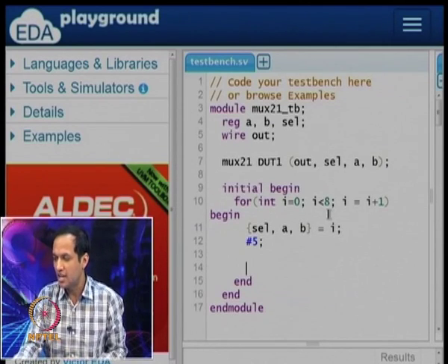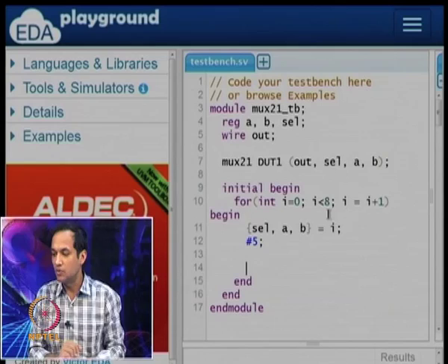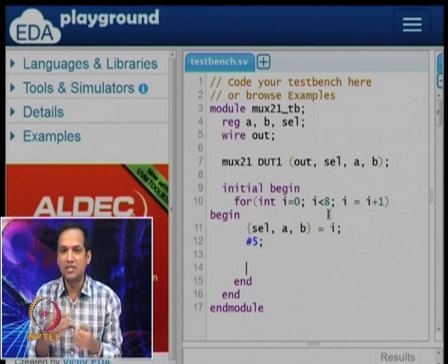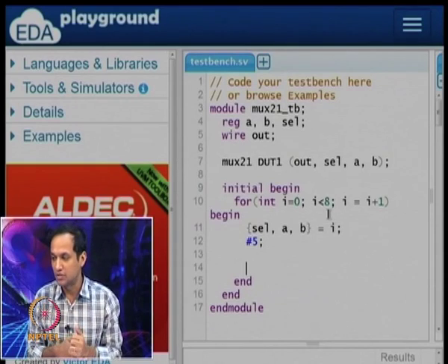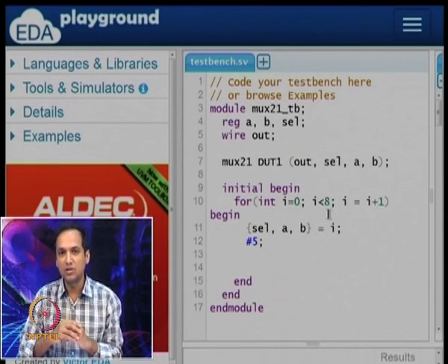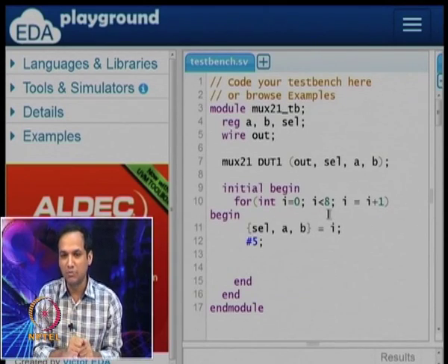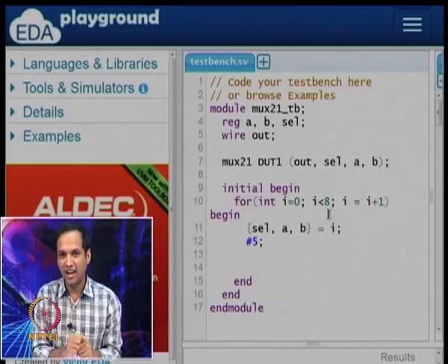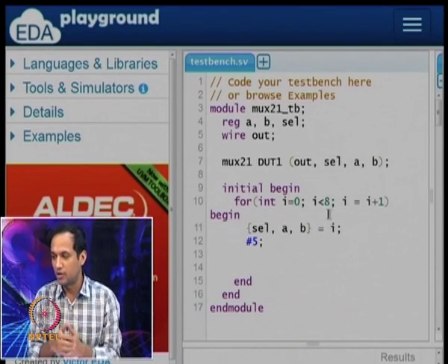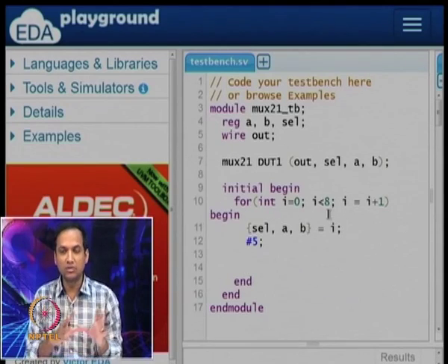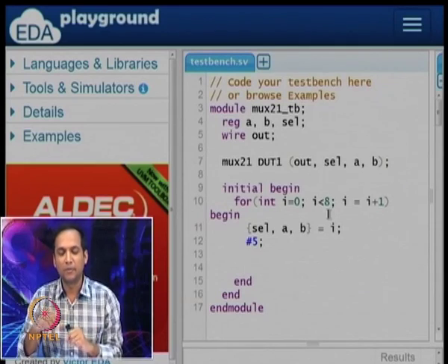On top of this I am going to do a few more things. One thing that we do for a test bench is that we can always go and visually see what the output is, we can see what the waveform is and so on, but sometimes it is also a good idea to actually know that this is what I am expecting from the design and am I getting the correct output or not. When we write the test bench modules, this is not something that you get from your breadboard, oscilloscope kind of setup.